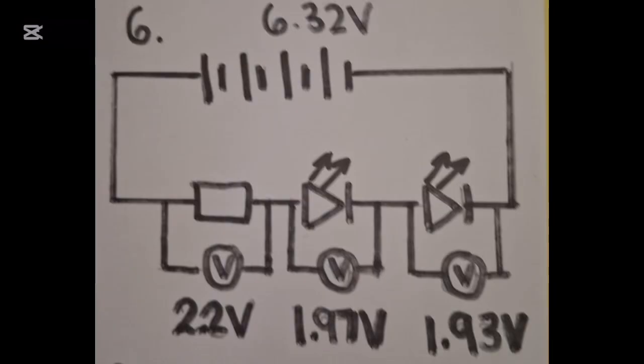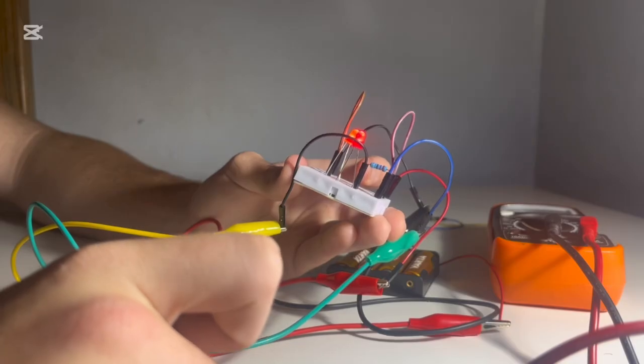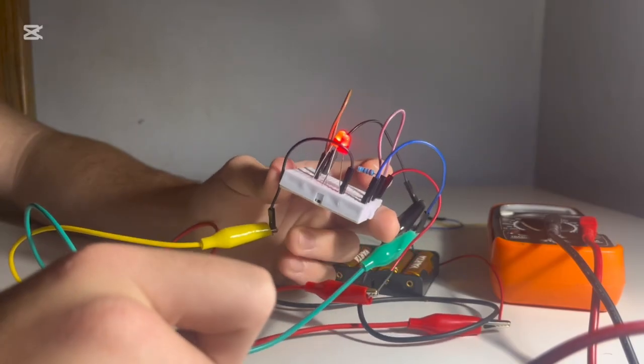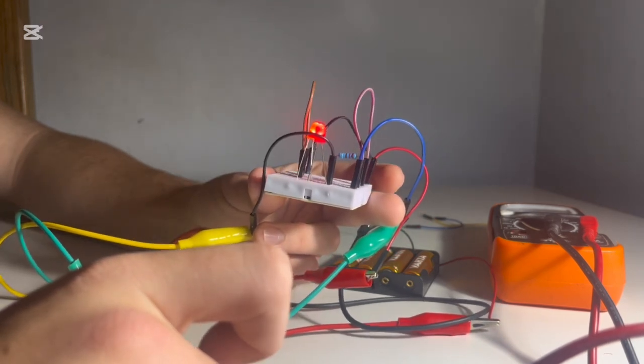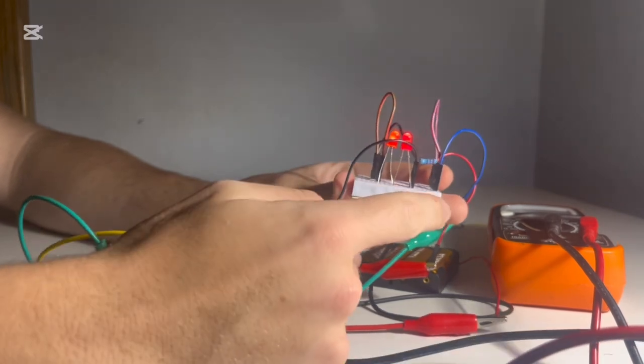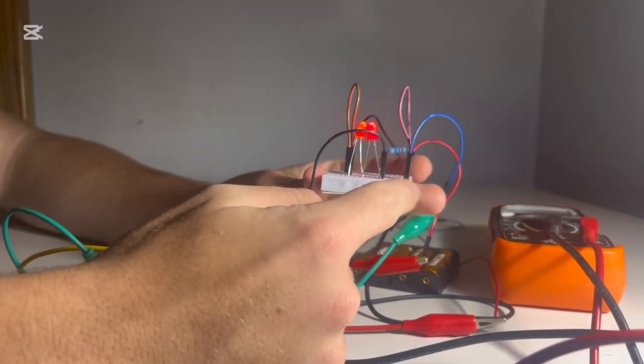Taking the same series circuit, we are now going to measure the voltage across each of the components in the circuit. A voltmeter has a very high resistance, and so we always place it in parallel to the part of the circuit we are measuring a volt drop across. We position the voltmeter parallel across the resistor.